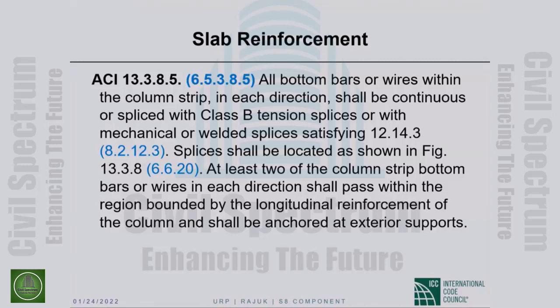It is not expected that everything will be the same as before the column got knocked out, but our expectation is that the slab should not end up on the ground or on the floor below. It should be hanging in place. And that requires structural integrity reinforcement. This is extremely important. And this is what the code requires.